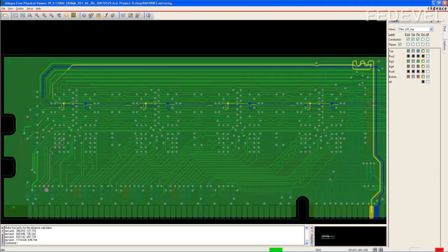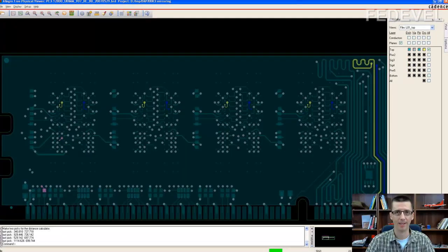Connecting the data lines in flyby topology is exactly the same as connecting data lines in the T-branch topology. It is just direct connection from the processor or FPGA to the memory chip. On this module, there are a couple of very interesting things what I would like to speak about. For example, they break one of the rules what you learned. Do you know which one it is?